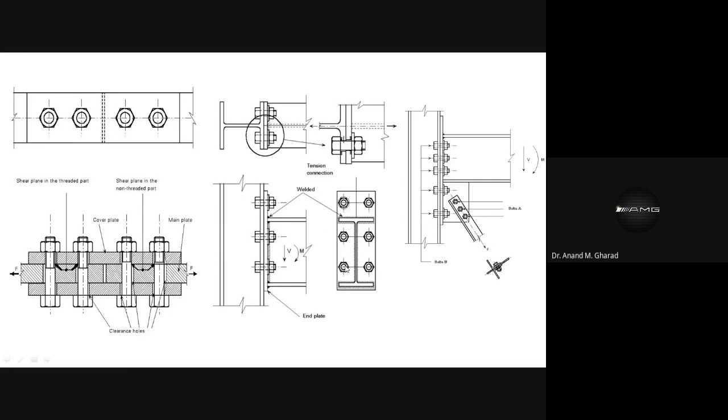One, two, three. Okay, on the other side similar connection is provided, and the cross section of the beam is I section, and the cross section of this column is again I section. Moreover, you will find this hatch portion. This hatch portion is nothing but the weld.